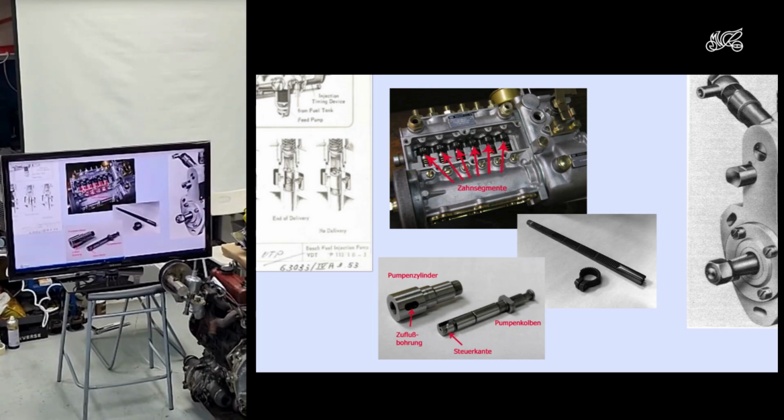So generally speaking, if a diesel pump stops working, it's because this rack thing has jammed up. Yeah. So it can also jam in the other direction on full throttle. And with a diesel engine, that's very dangerous because the engine will just run away and explode. So, yeah, but it's quite precision technology.